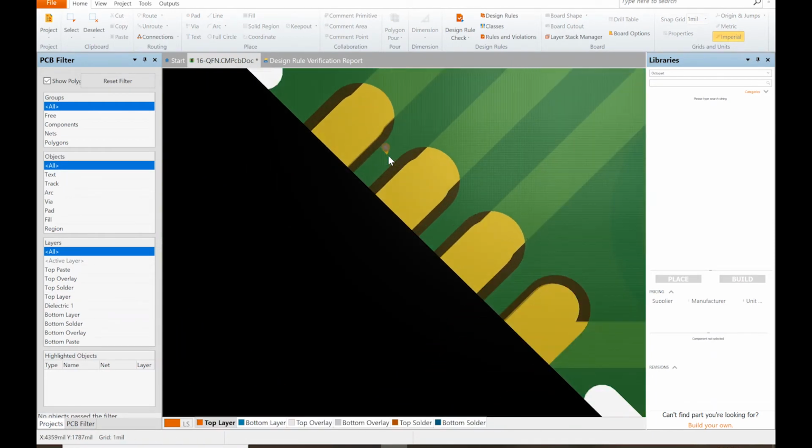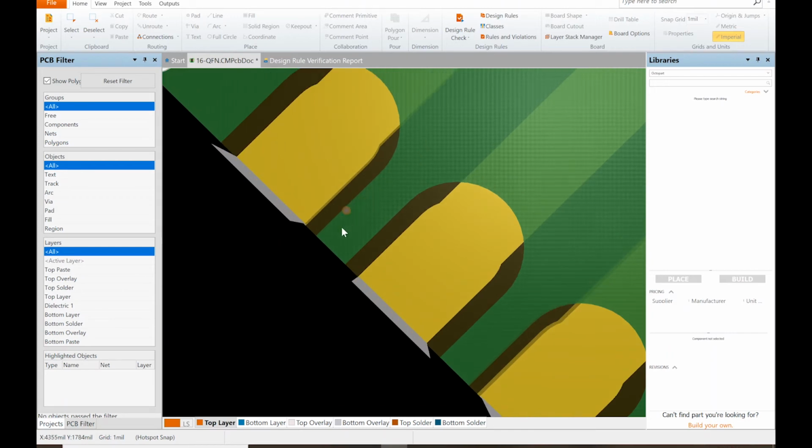So here, as you can see before, we've actually made this sliver a little wider. The advantage of that is that when you actually apply solder to this, the solder mask really prevents the solder bridge from occurring between these two. So having a solder mask in between here is definitely something that we want to have.